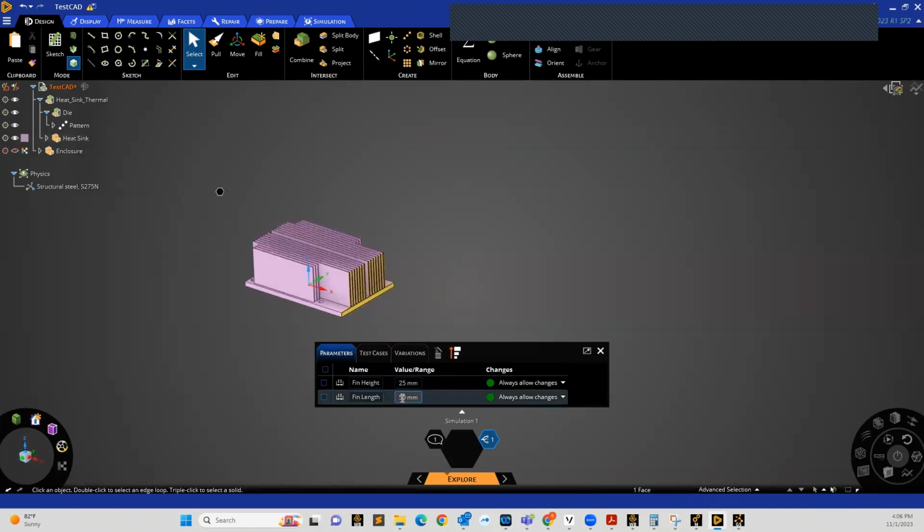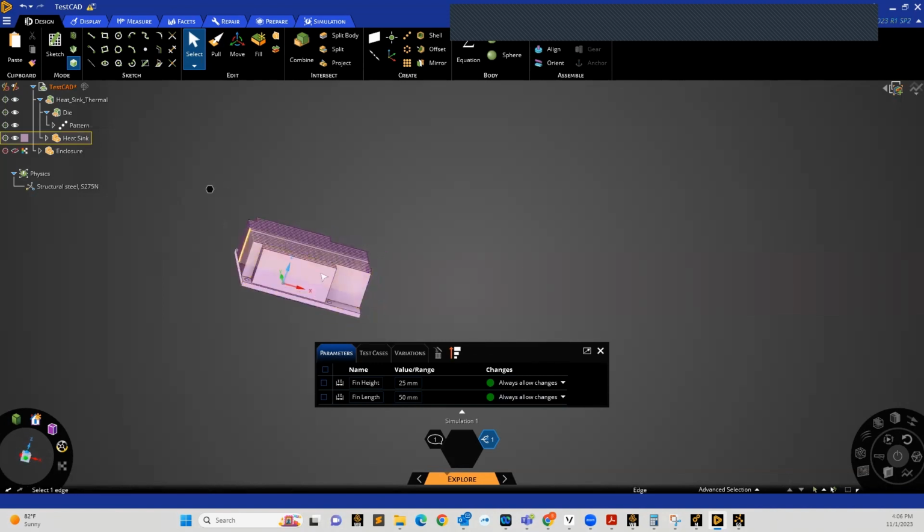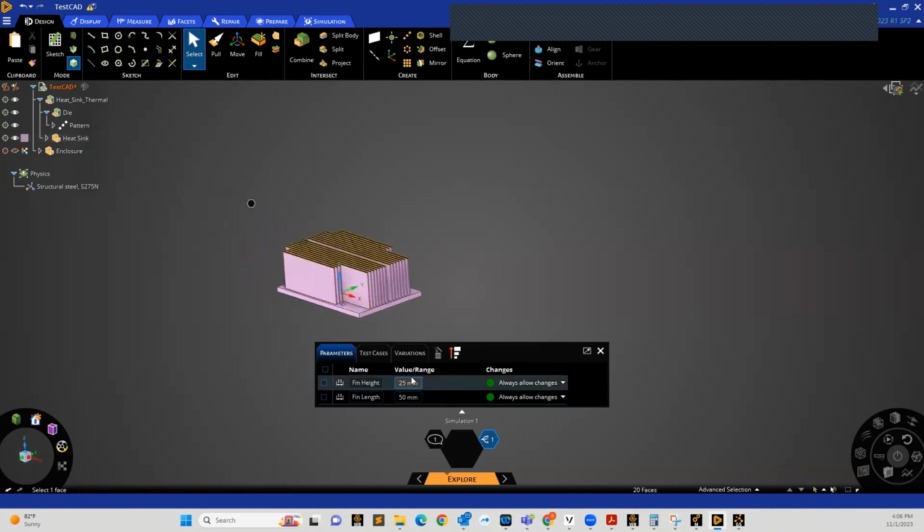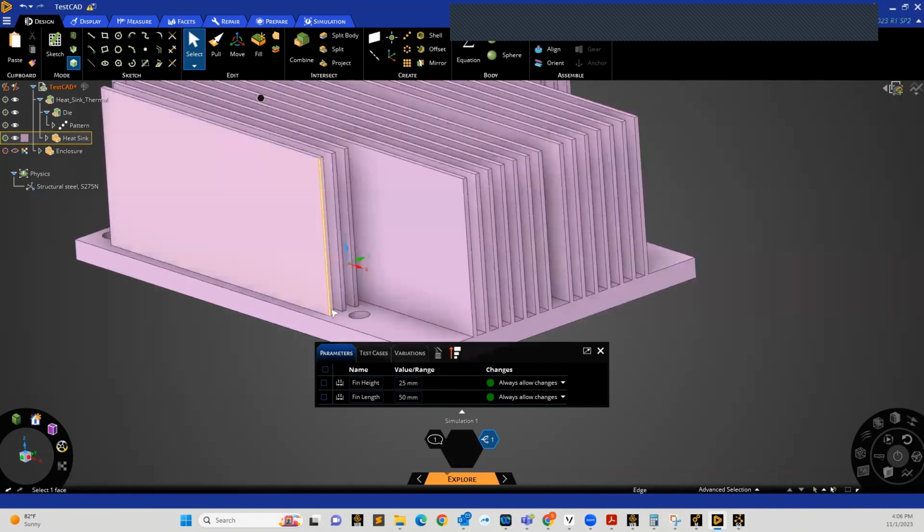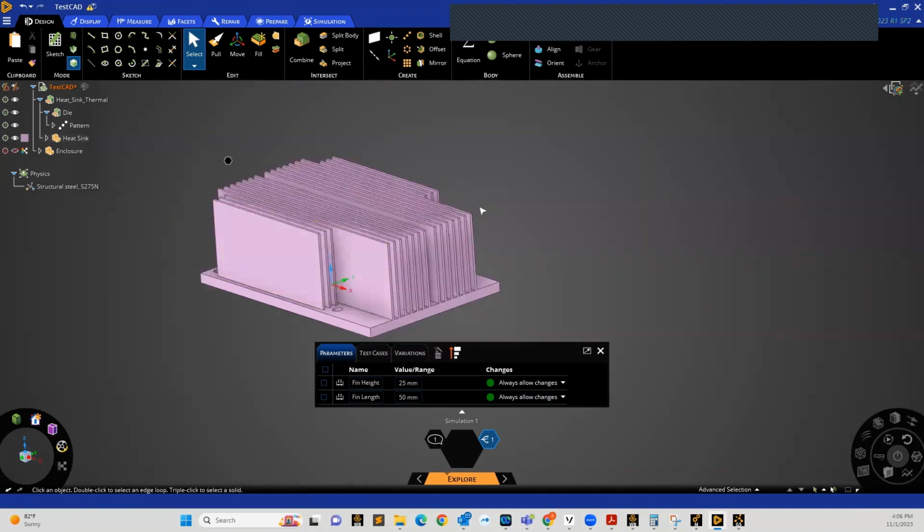So that's another way that we can go about defining parameters that don't necessarily have a reference on the actual CAD model like I did with my first parameter, right? In this example, what we're doing is we're referencing the origin instead. You can also choose to reference different points like we showed on the heat exchanger itself. So you'd be able to pick, for example, maybe this surface here on one of these fins, or some intermediate surface on any one of these, kind of perpendicular here, these wide surfaces, etc. It just kind of depends on what kind of parameter you'd like to set.